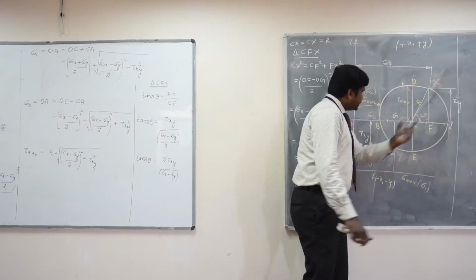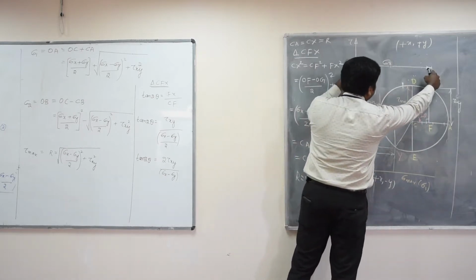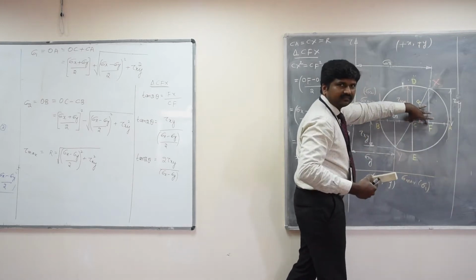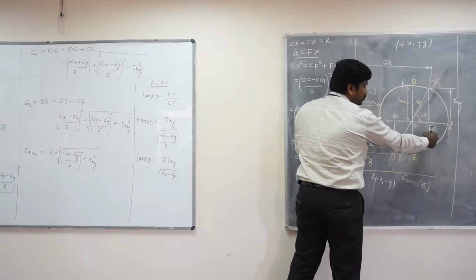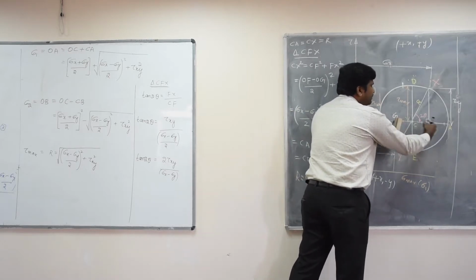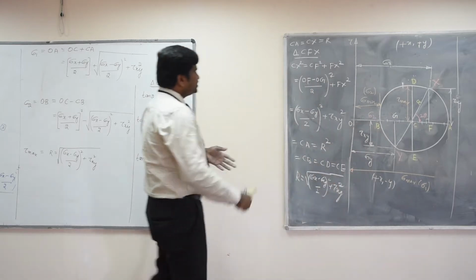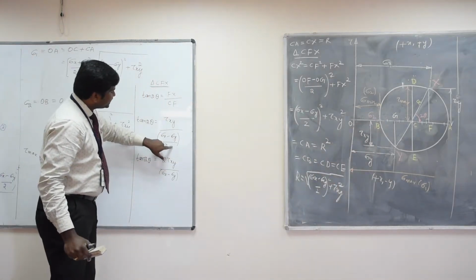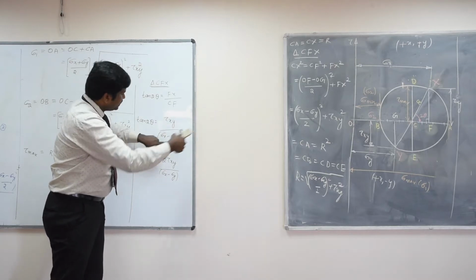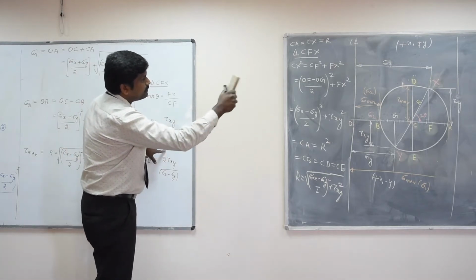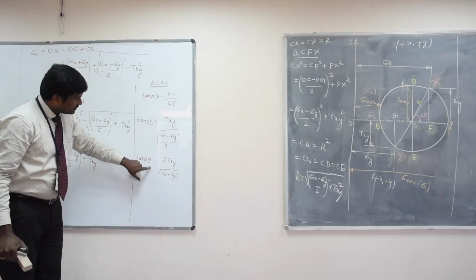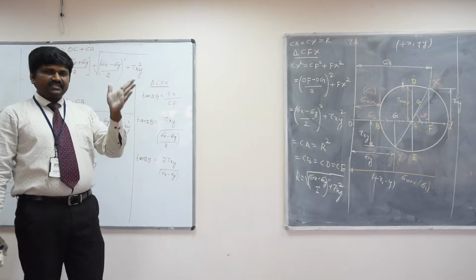Then what is CF? CF you can find if you know OF minus OG, you will get FG, and half of that will be CF. That means O to F, this distance minus this distance, and half of that distance will be this, right? So OF is sigma x, and CF is (sigma x minus sigma y) by 2. That is what is equal to (OF minus OG) by 2. That is this equation. After simplification, you will get the tan 2 theta equation. So with this equation we can find out the plane in which the stresses are maximum.